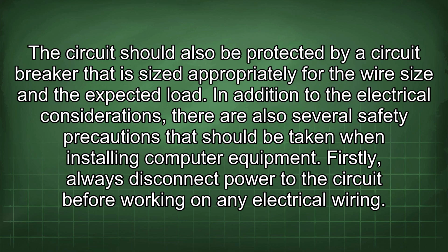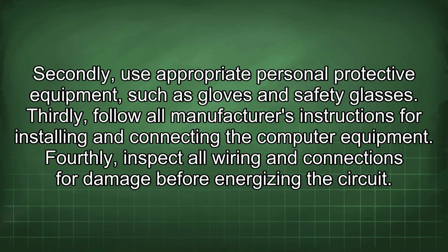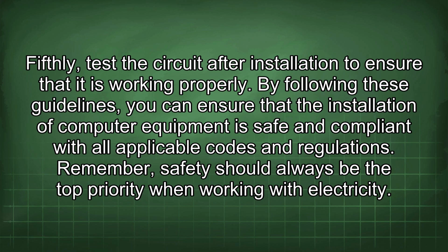expected load. In addition to the electrical considerations, there are also several safety precautions that should be taken when installing computer equipment. Firstly, always disconnect power to the circuit before working on any electrical wiring. Secondly, use appropriate personal protective equipment, such as gloves and safety glasses. Thirdly, follow all manufacturer's instructions for installing and connecting the computer equipment. Fourthly, inspect all wiring and connections for damage before energizing the circuit.